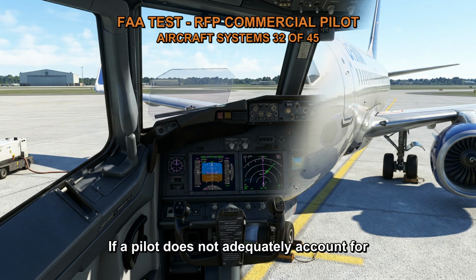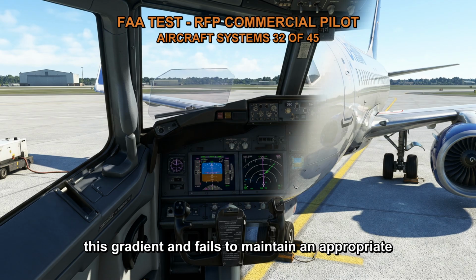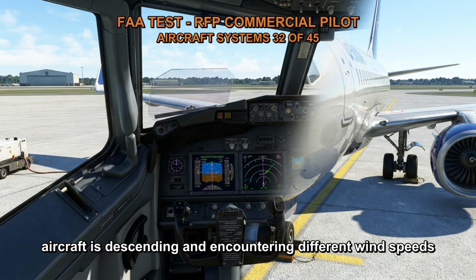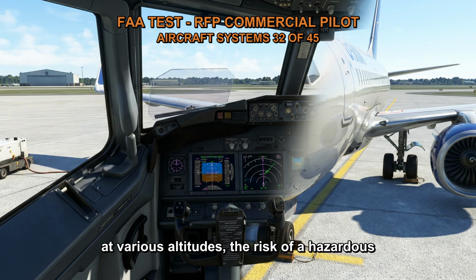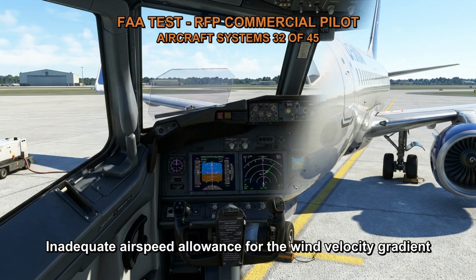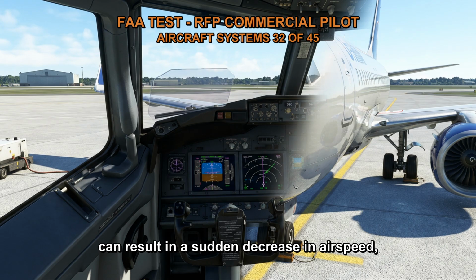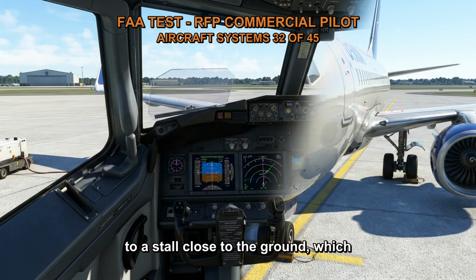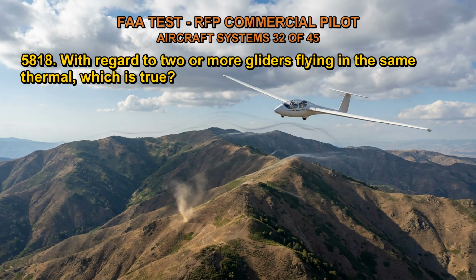If a pilot does not adequately account for this gradient and fails to maintain an appropriate airspeed, it can lead to a dangerous situation. During the approach to a landing, when the aircraft is descending and encountering different wind speeds at various altitudes, the risk of a hazardous stall increases if the airspeed is not properly adjusted. Inadequate airspeed allowance for the wind velocity gradient can result in a sudden decrease in airspeed, increasing the angle of attack and potentially leading to a stall close to the ground, which can be particularly dangerous.